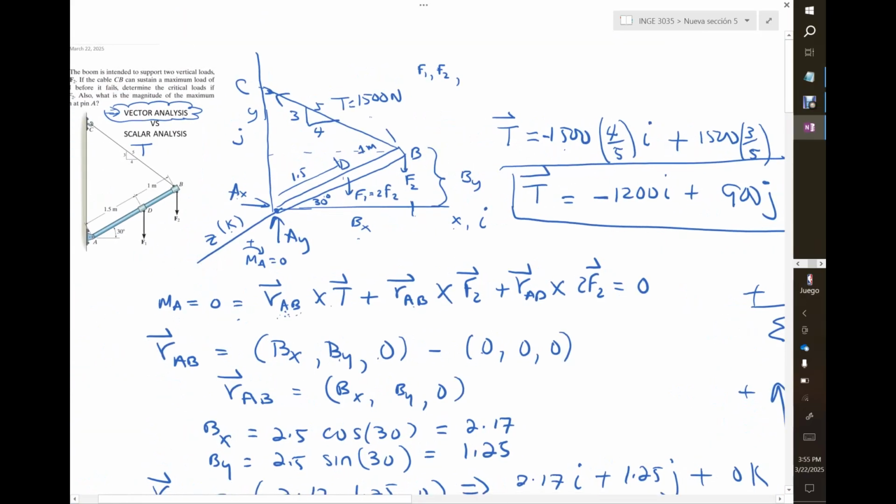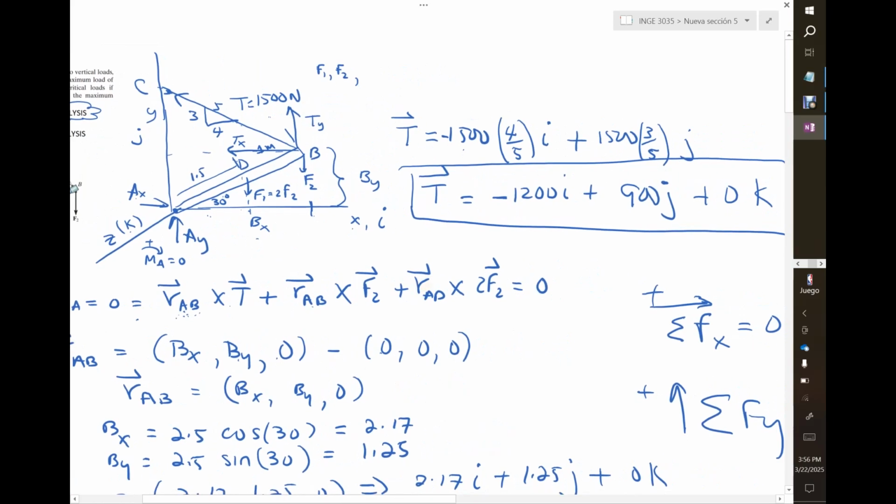using scalar analysis, it's very straightforward in that I only need the perpendicular distance between this vector here and this distance, which I already calculated. I need to break this one in two parts, one going up, which I'll call, for example, ty, and one going this way, which is called tx. So we need these two. We already know them because they are right here.